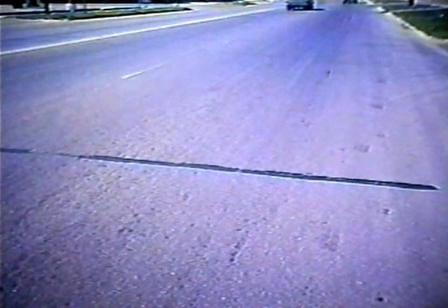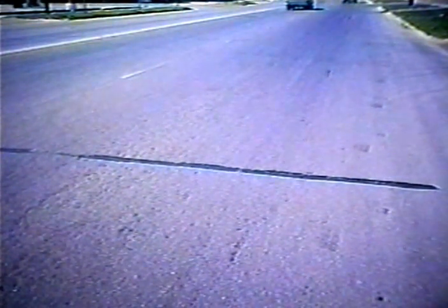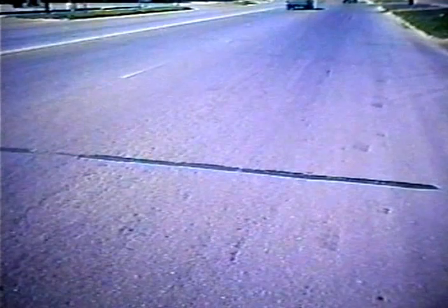If we begin with transverse cracking, what we're really talking about here is a crack that's perpendicular to the center line. Those are usually the first types of cracks to appear. And if you think about an asphalt pavement, it's a long, narrow strip of asphalt. It's expanding and contracting with changes in temperature. And you will get a transverse crack developing perpendicular then to the center line. It's a normal thing. It's going to happen in all of our asphalt pavements.